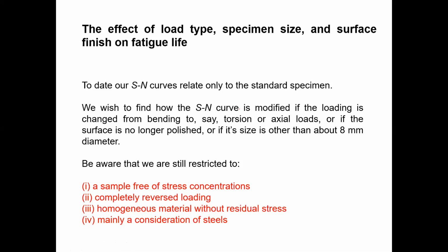If you get a different surface without mirror polish, like a hot rolled sample or cast sample, or an annealed sample, and the surface finish is different, we can't get the comparison again. So that's why we need to keep one single method to finish the surface. Otherwise, the fatigue lifetime will vary with the surface finish. So these are some of the parameters that govern the fatigue life.